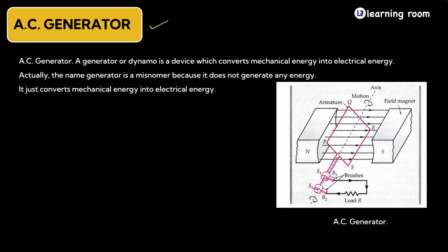Okay. So as the name suggests, what is a generator? Something that can generate voltage, right? But what kind of voltage is it going to generate? It is going to generate AC. So it is going to generate an alternating voltage, meaning a voltage that will have a change in its direction with respect to time. If that should happen, the first thing is this AC generator is supposed to be a device that works on the principle of Faraday's law of electromagnetic induction,